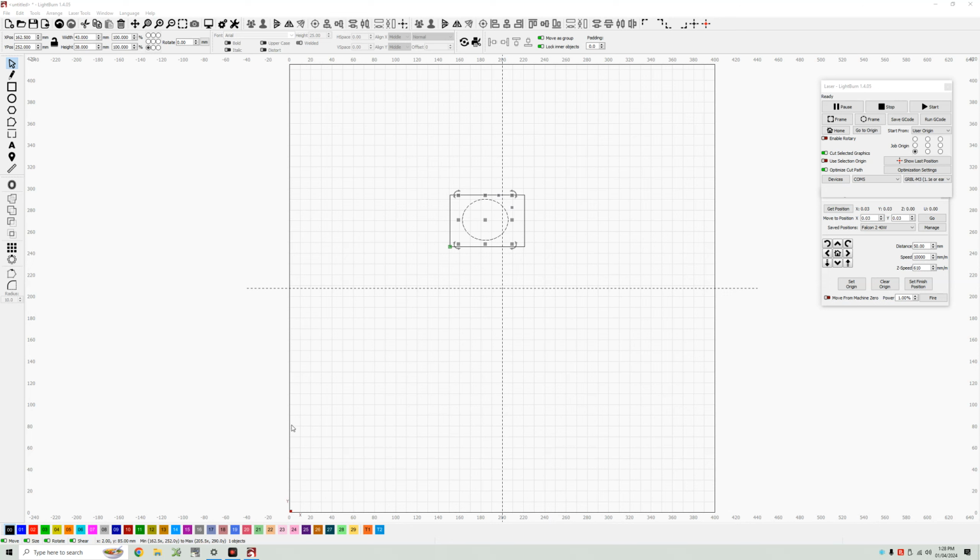So in any wasteboard situation where you have a fixed home point, which is what we're going for, we don't ever want to have to measure or reference or frame or any of that nonsense. We're just going to put everything down here and it's going to burn perfectly to the measurements. We can send the laser over and burn something 10 millimeters over and 50 millimeters up, or whatever we want. So to make this match your wasteboard, even if you got my thing or you made your own, you need that to coincide with your 0 point in the physical location.